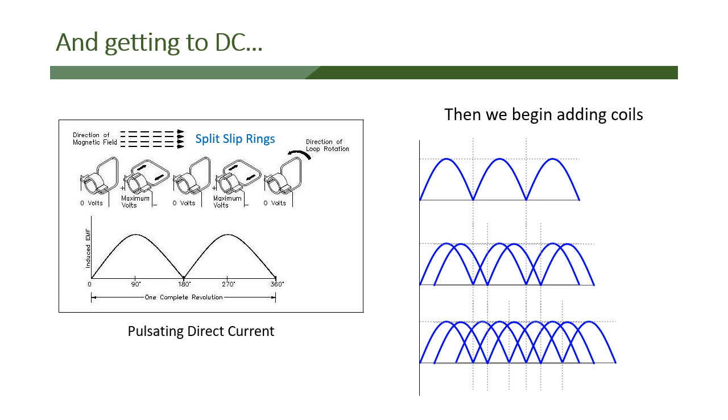So for the first top illustration, let's assume the average voltage across the time of the first cycle, from 0 peak to 0, is 50%. We add a second sine wave to that, and you can see they algebraically will sum, and we're going to get something higher than 50%. When we add a third sine wave, the average will go up further to much higher than 50%, maybe 75 or 85% of what the potential peak could be over time. And so that's how we create an approximation of DC.